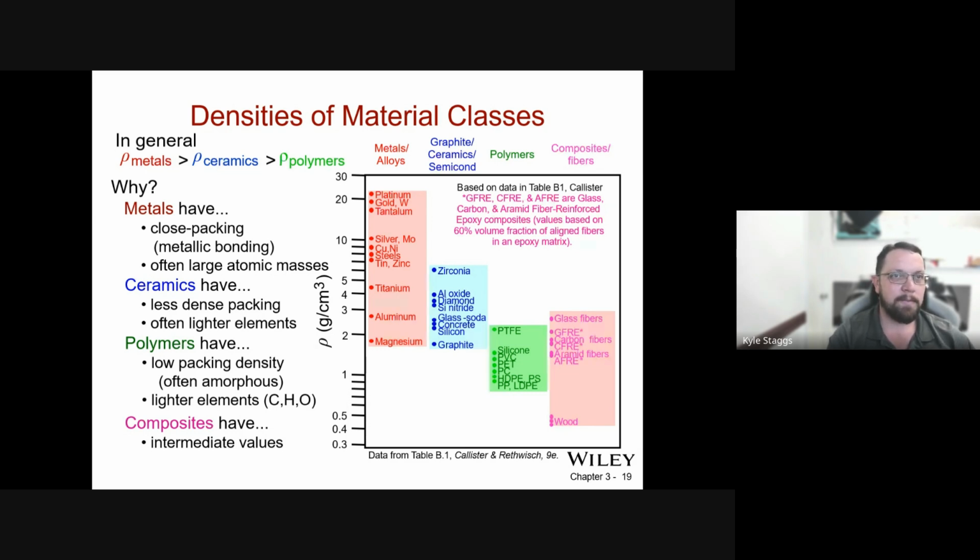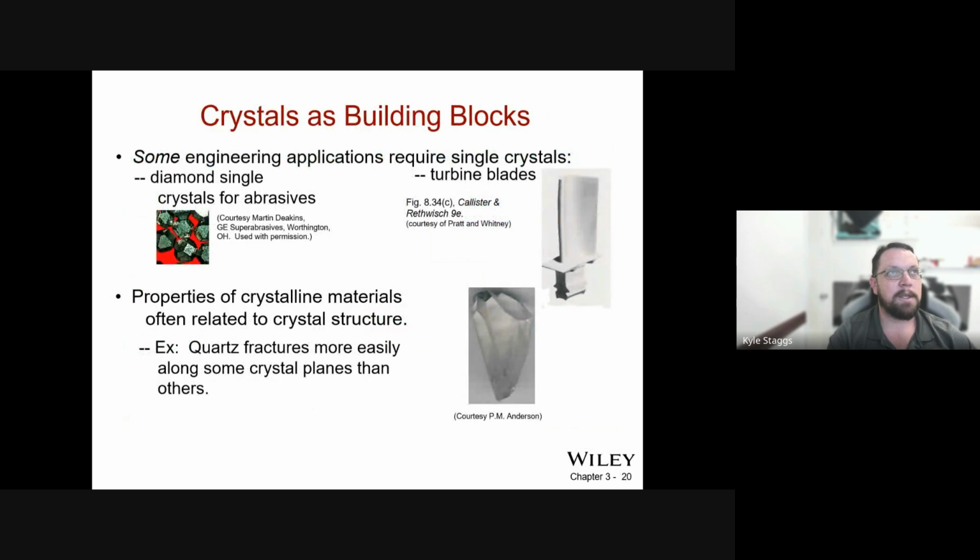So the way that the composites are made, the way that the fabric layups are done, types and amounts of resins used, whether or not it's cured in an autoclave, whether or not it's vacuum bagged, and all of those sorts of things. All of that makes quite a big difference.